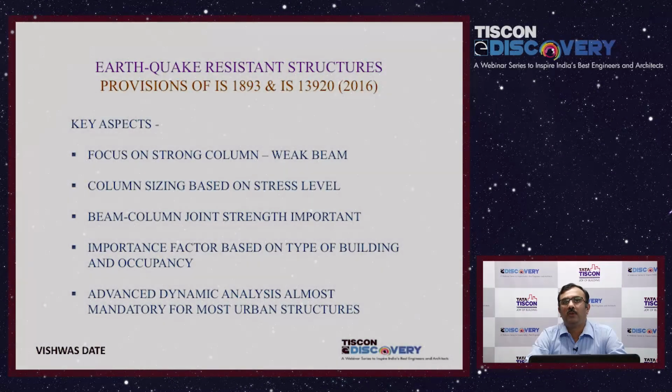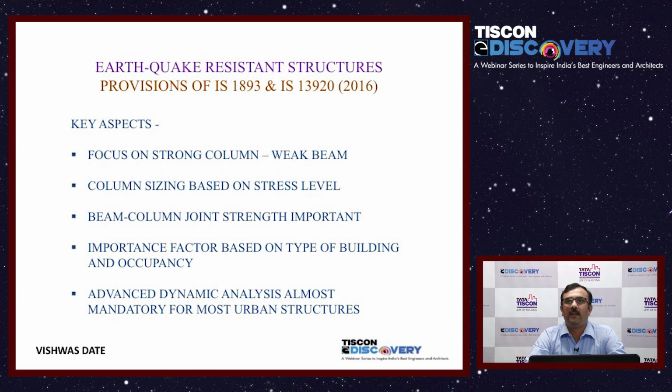And that's why we should look at the provisions of the new earthquake code and understand that they have come from our historical understanding of the behavior of buildings, understanding of what earthquake force is, understanding of how it affects our building. So if you look at the new codes, you can clearly see the focus is shifted, or rather very prominently placed, on strong column weak beam theory.